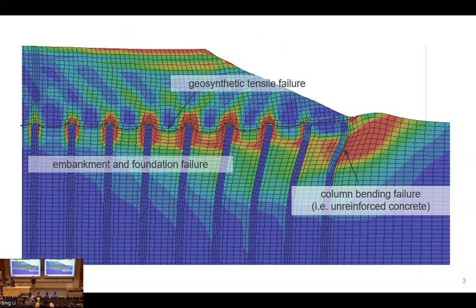You mentioned that you've done a lot of 3D modeling. At what point do you think, in your opinion, it's worth jumping to 3D rather than applying 2D? Before you jump into any 3D analysis, you should think about whether the problem can be simplified in any way into 2D. There are situations where you simply cannot, depending on the geometry of your model, site conditions, the loading conditions, and boundary conditions. Sometimes it may be best to use 3D analysis, but that depends on your techniques, obviously.